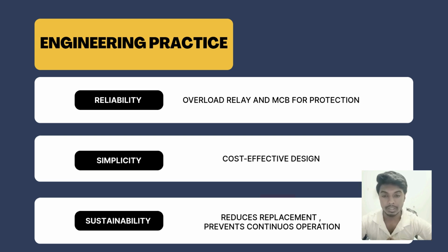The control logic, where the thermostat signals the contactor to energize the compressor and fan, represents a fundamental and widely accepted method for residential HVAC systems, directly responding to the thermal load. Sustainability is implicitly supported by protective measures like the MCB and overload relay, which extend equipment life and reduce replacement frequency, and by the on-off control contributing to basic energy efficiency.